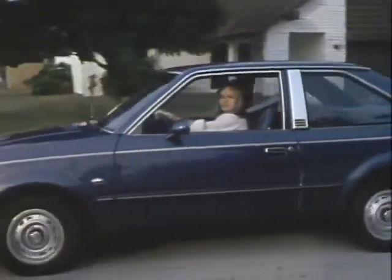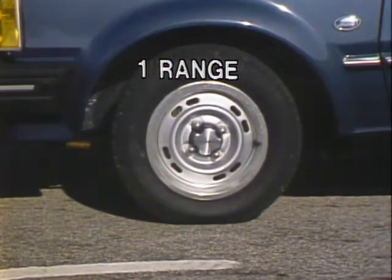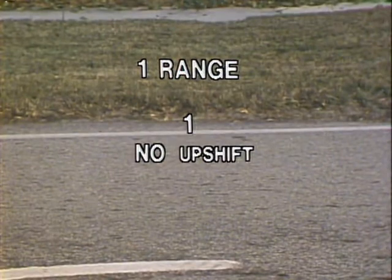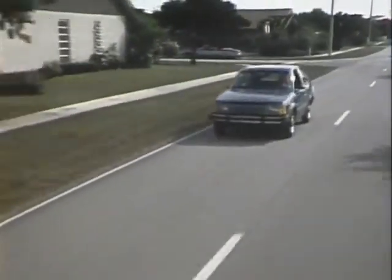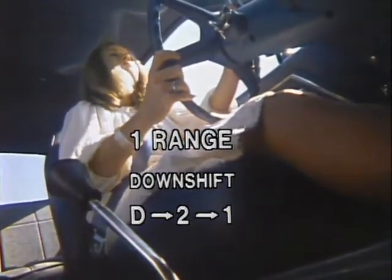If the car is stopped and the selector is placed in range 1 or manual low, the transaxle starts in low gear and stays there. Manual low gear has a clutch applied for engine braking. If the car is moving at road speed, and then the selector is moved from D to manual low, the transaxle will downshift to second, then, at a lower speed, to manual low.